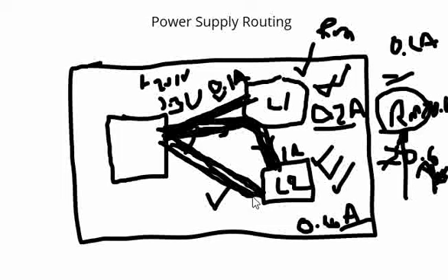So if you are dividing your placement into various areas where you have a load 1, you have load 2, or several other areas, and you cannot have a power plane, the best option would be to do a star routing in these scenarios. So this is one of the important tips while routing. If you have encountered such scenarios